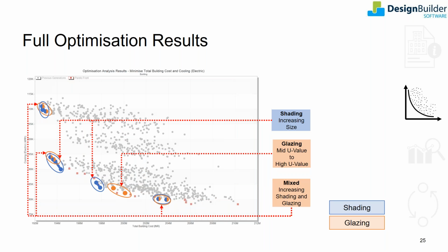Relative trends of glazing versus shading were the most difficult to analyze because in most of the cases, 2 to 3 variables were changing at the same time, such as glazing, shading on one of the facades, and solar absorptance values. For the shading, some of the trends found suggested we could achieve high energy reduction impact for relatively low cost. Assessment of which shading works best for which facade based on this analysis was inconclusive and required many more data points.